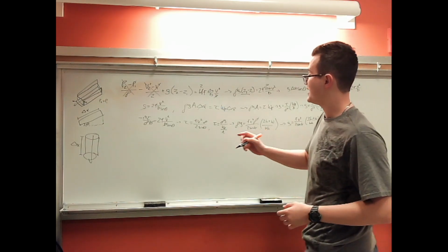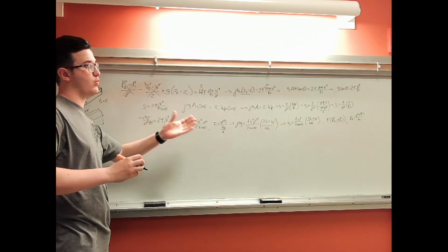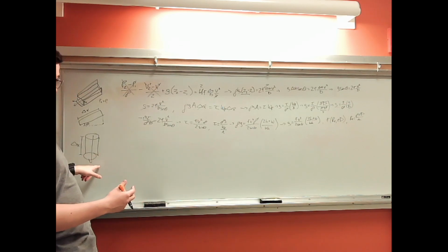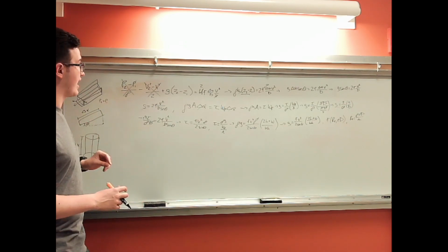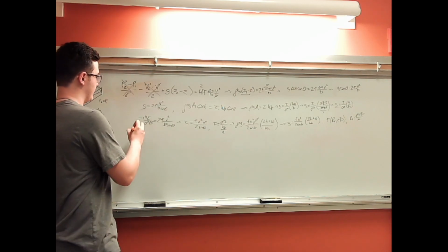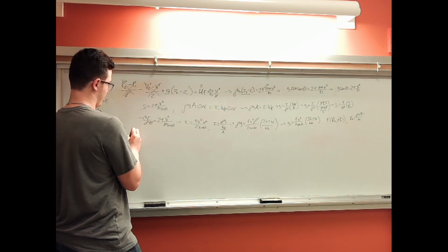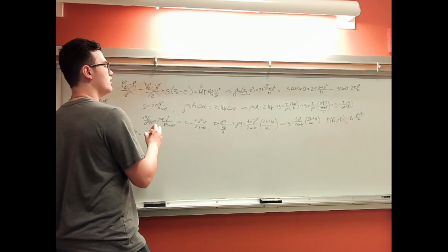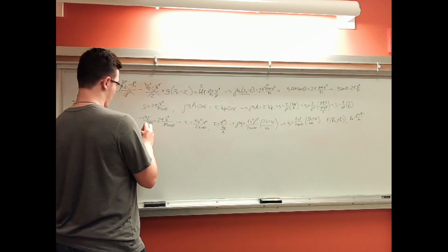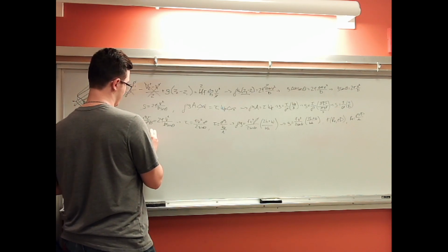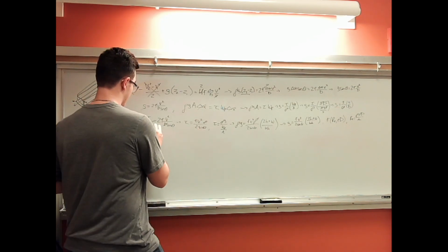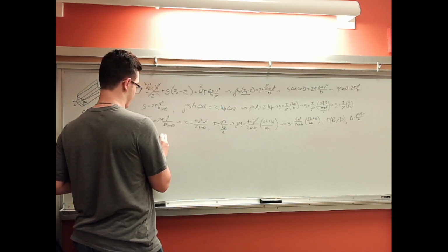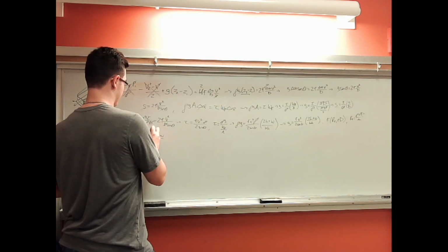So we have this wetted perimeter divided by area, which we know is the same in both the circular approximation and our actual real situation. So wetted perimeter divided by area is equal to, we found this earlier, 4 divided by the diameter. It's also equal to, as we found earlier, 2 times the height plus the width divided by the width times the height. That means that these two cancel.